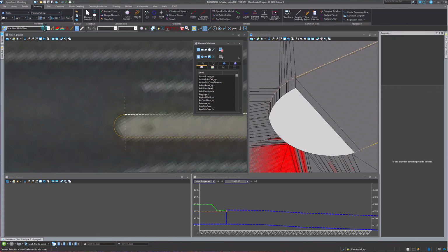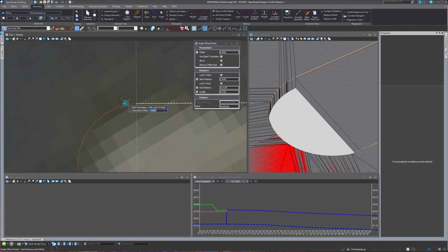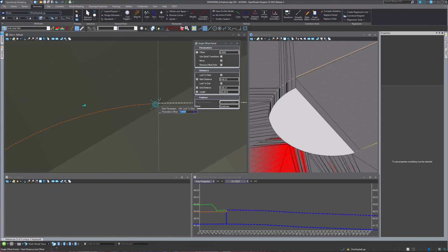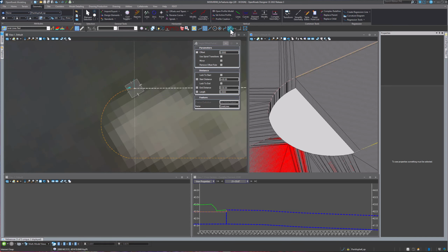Now I'm at 300 and I'm just going to go find my construction lines red. And we'll do a single offset partial. And I want to go just from the beginning of this existing traffic separator, swing around, and I'm going to turn on my intersection snap, and we're going to snap right there.